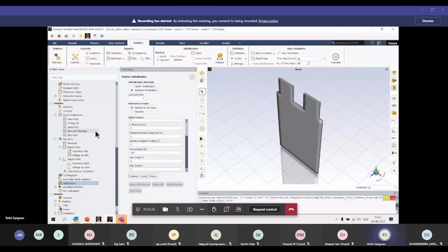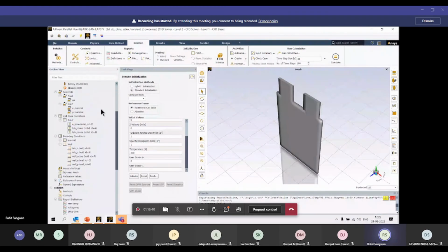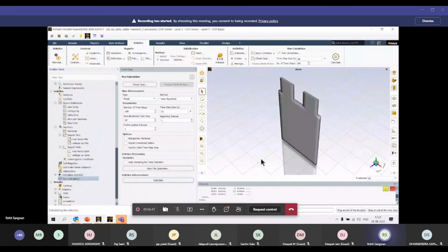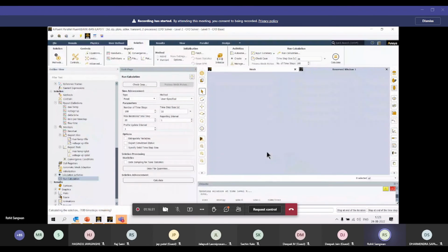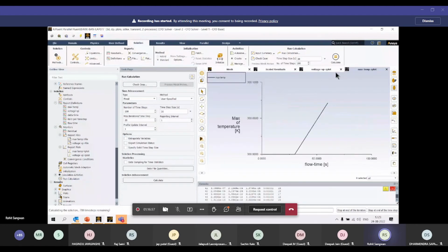I initialized in steady state, that's why it is showing an error. So now we'll go for run again. And now you can see the temperature graph and voltage plot with respect to time. This information is very critical when we check validation with respect to our practical work.